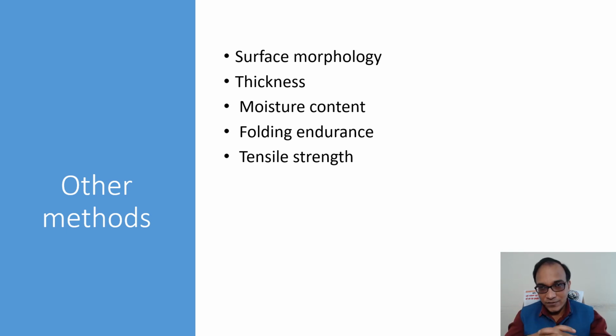So it means 370 is the folding endurance of that film. That's a very simple evaluation parameter. Then tensile strength, as we have mentioned, as shear strength can be measured in the same way, tensile strength can be measured. The tape can be hung to a tensile strength apparatus, and the weight can be increased. The weight required to break that film may be indicative of tensile strength.